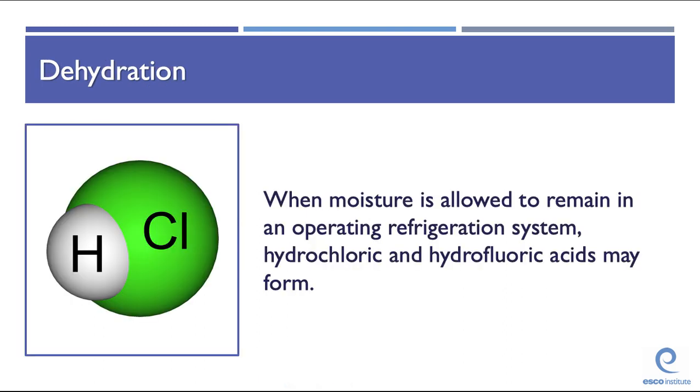If moisture is allowed to remain in an operating refrigeration system, hydrochloric and hydrofluoric acid may form. Evacuation of a system is the suggested method of dehydration. It is not possible to over-evacuate a system.